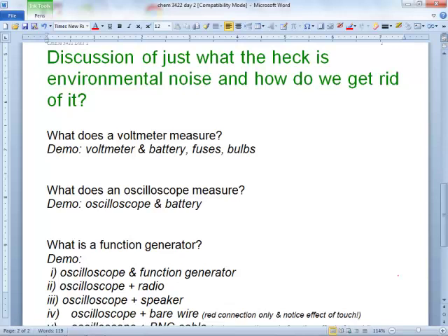Someone said it. You're close. Ohms. Put it on the ohms. You're going to measure resistance. And the trick to it is, if there's no resistance, in other words, touch metal to metal, what does it read? Close to 0 or something, doesn't it? But it's bouncing around. You get a reading.